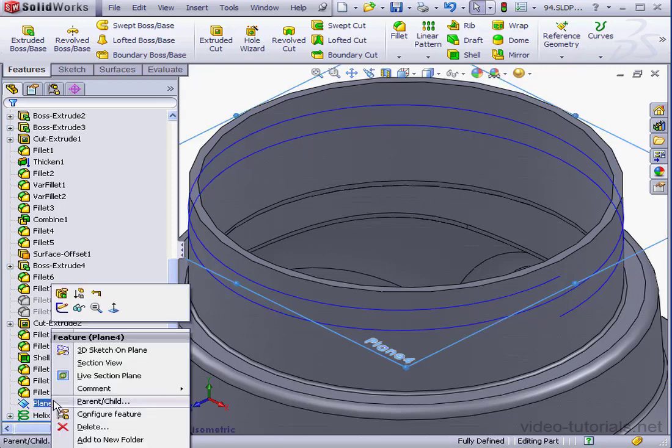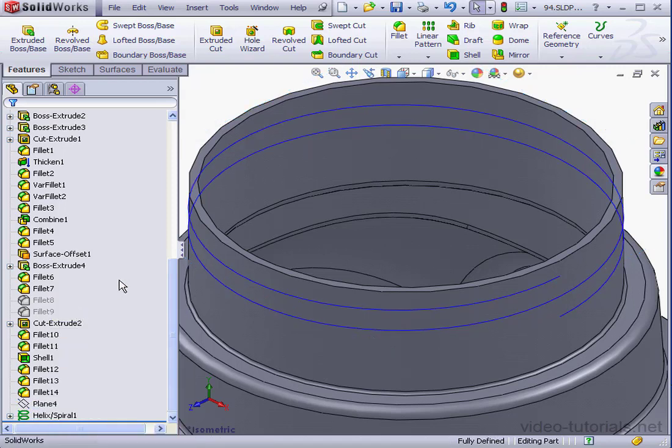And let's hide our plane. Right-click, Hide Plane 4. Next, we need to terminate the thread inside the neck body. In the first volume of our Solidworks library, we learned how to do this using a multi-body solid. In this lesson, we're going to try a different approach. Let's begin with a sketch.